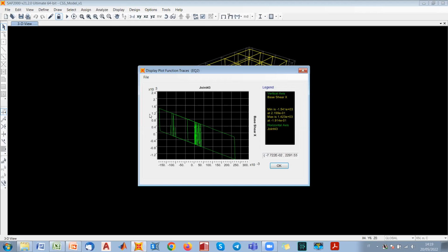So this is what I meant yesterday. Maybe by looking at the results of the single degree of freedom, also here we will see some events which have a larger displacement demand with respect to design, and most of them will have a lower value, just because, if you remember, the last event has a huge displacement demand, but at the end we have the spectrum compatibility, which is checked for the suite that we have adopted.